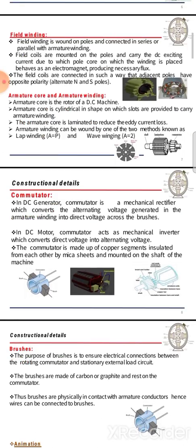Another one is brushes. The purpose of brushes is to ensure electrical connections between the rotating commutator and the stationary external load circuit. The brushes are made up of carbon or graphite and rest on the commutator.